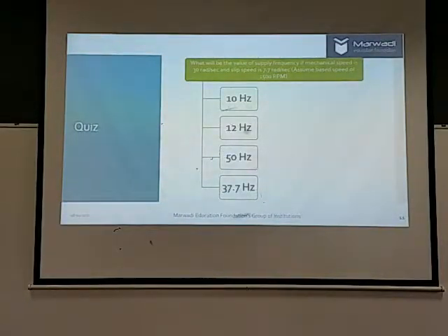Okay, fine. Now we can understand that this is 30 radian per second and the slip speed is 7.7 radian per second. Now 1500 rpm is the base speed. That means at 50 Hz we will get 1500 rpm, which is near to 157 radian per second. So based on that, we will get 12 Hz as the output. That means if you want to obtain 30 radian per second as the mechanical speed, with 7.7 as the slip, then we need to supply approximately 12 Hertz.